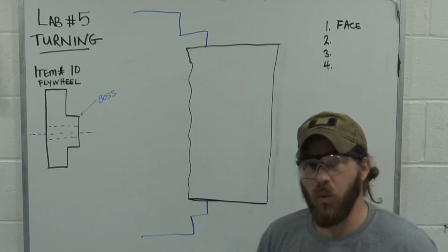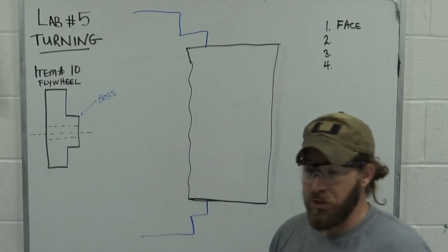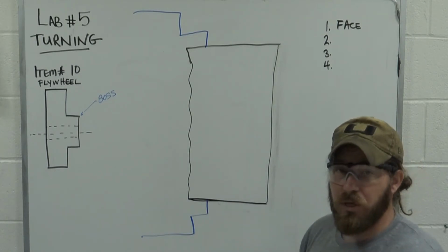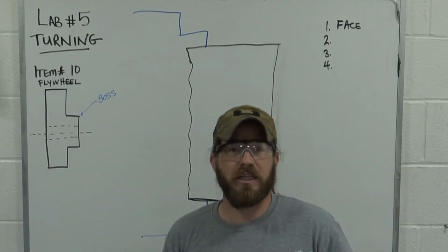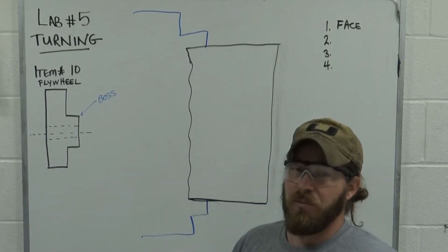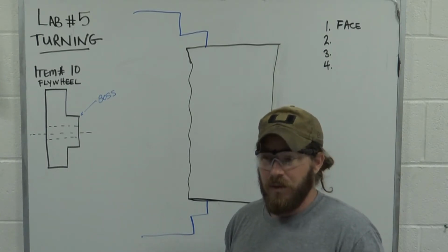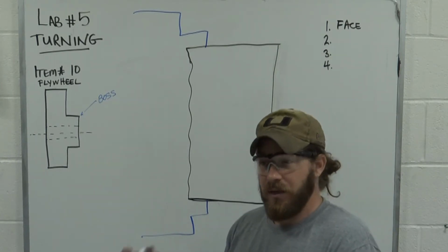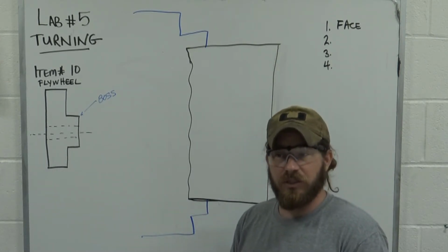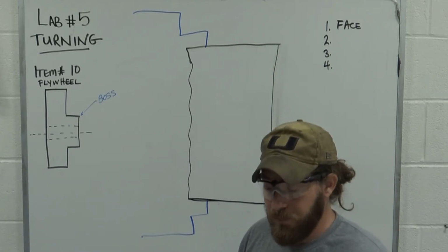All right, so we've got a one-way, one-sided tolerance, or unilateral tolerance. When you see a hole dimensioned in 4 decimal places, what should your mind automatically think? Your mind should already jump to, I have to ream this, right? Because Brian told you that the drills do not drill on a tight enough tolerance. So we're going to have to drill and ream this, all right?